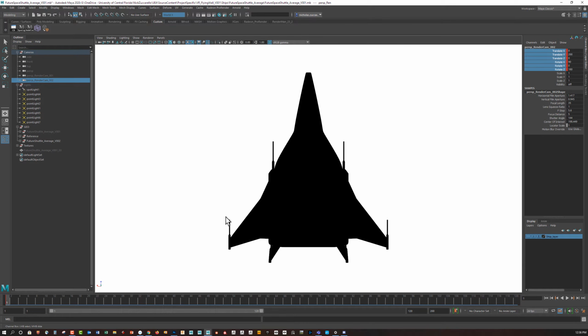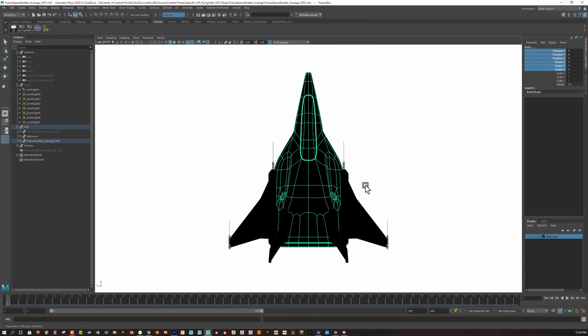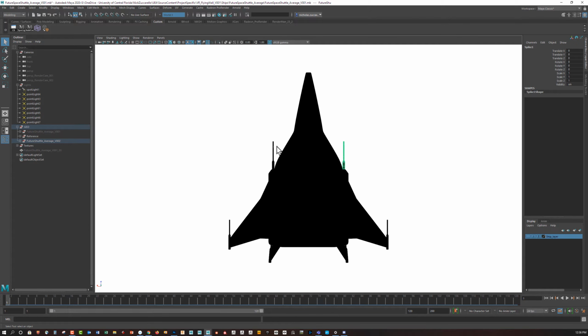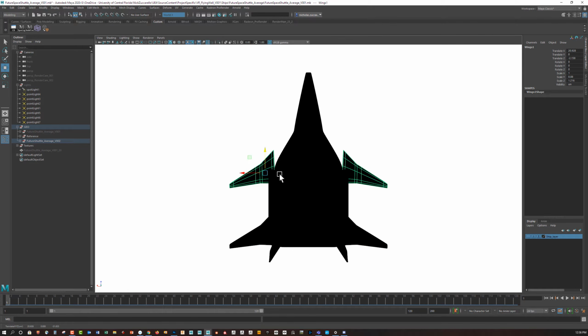Okay, so this is completely up to you. As you've duplicated this thing off and you want to change the design, you can add or subtract as many pieces from this as you want. So maybe I'm getting rid of this, hitting Control H for these things, I'll hit Control H for that. I've got these wings on here. You're free to make your own shapes for wings. Let's say I wanted to pull these down. I can hold down Shift to duplicate these out.